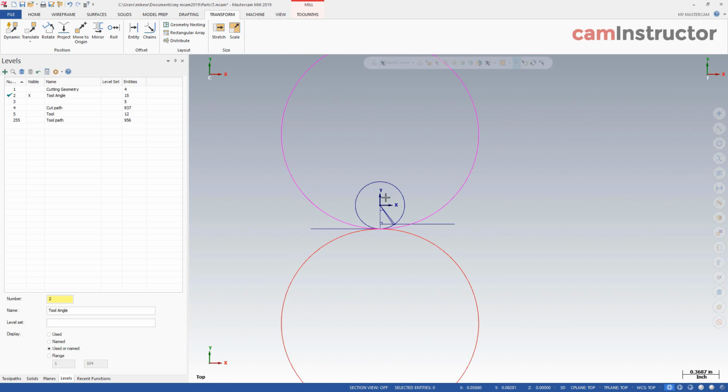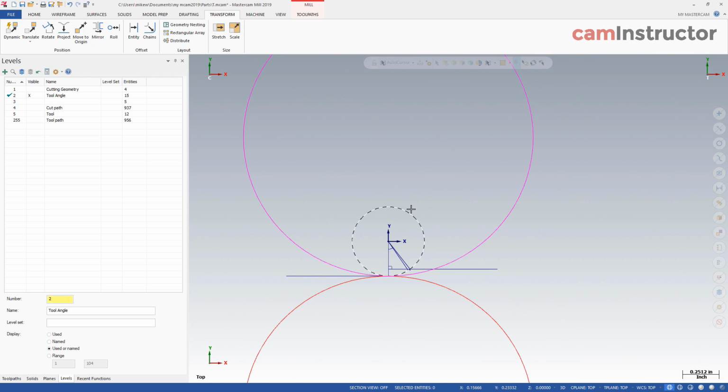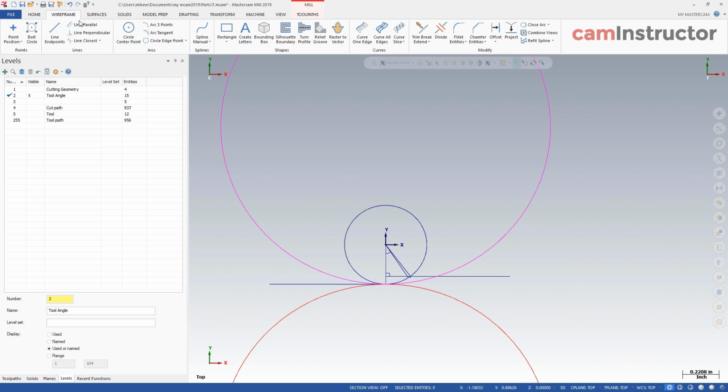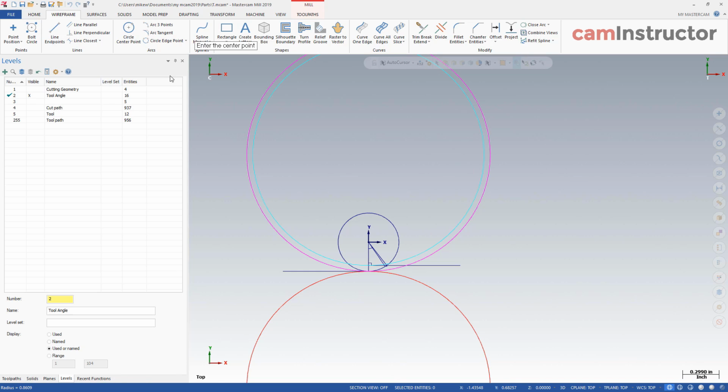So scenario number 2 is when the material or cut path actually goes up in the direction of travel. So this time our cut geometry is going to be smaller than our tool. So we said 50 thou depth of cut. So this gives us 1.9 diameter on this type of guy.